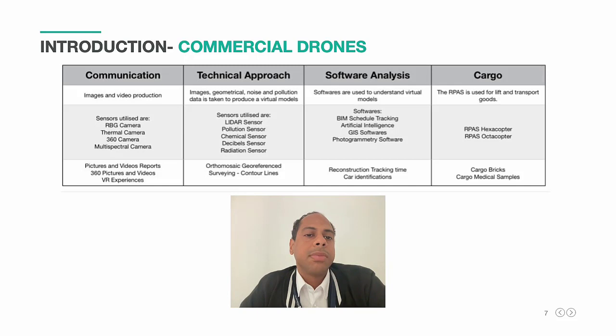And then we have the multispectral camera, with which we can identify the different types of vegetation that we're going to face in a specific construction site, in order to get environmental permissions. We can create a table assessment of the type of vegetation, the plants, according to the spectrum of images that it's reflecting to the sensor.